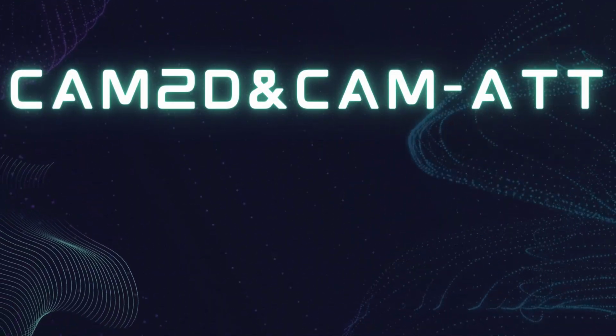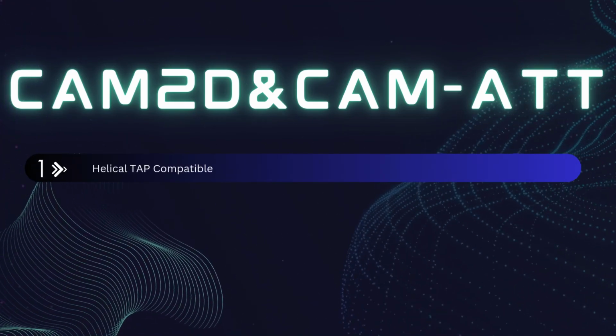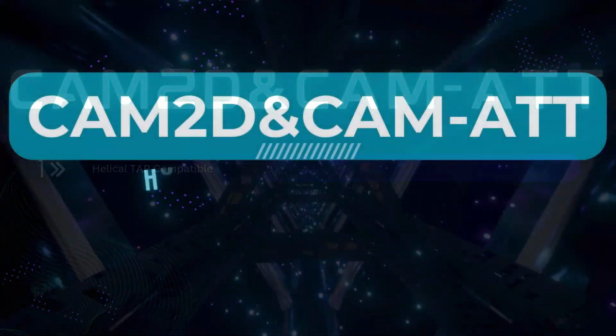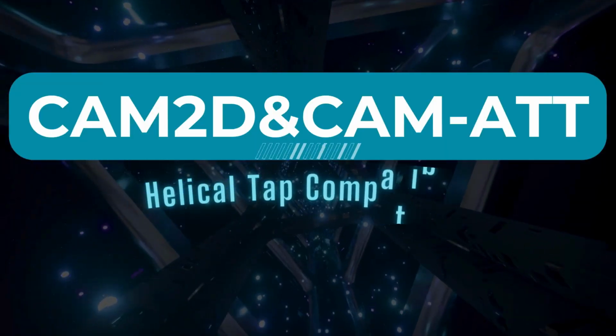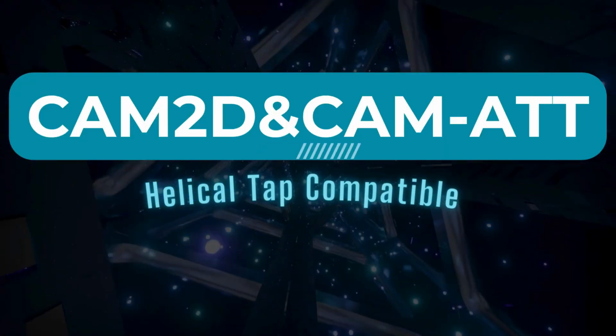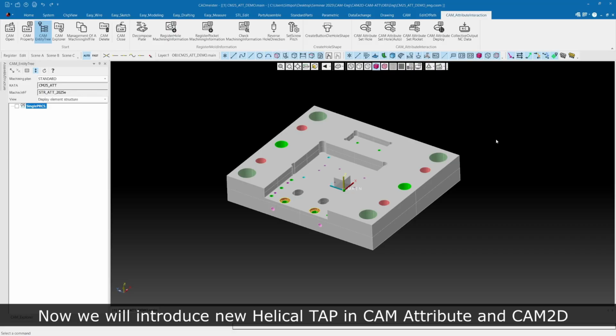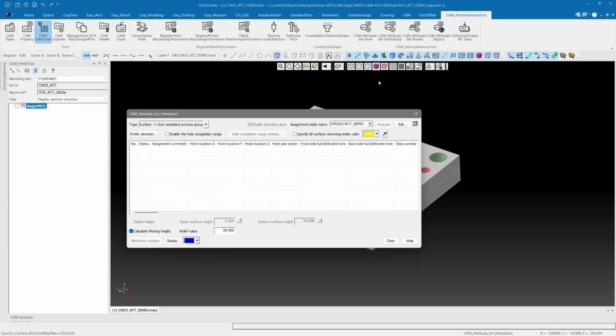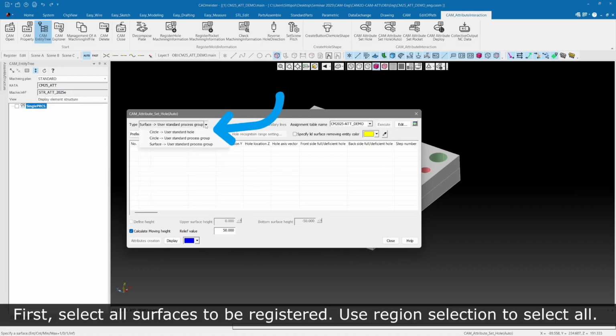Next is the CAM 2D and CAM attribute section, which includes one important improvement. Helical tap compatible. It is now possible to create toolpaths that support helical tapping using a thread mill. To begin, open CAM Attribute Set Hole Auto to automatically create the machining process. First, select all the surfaces that need to be registered as holes.